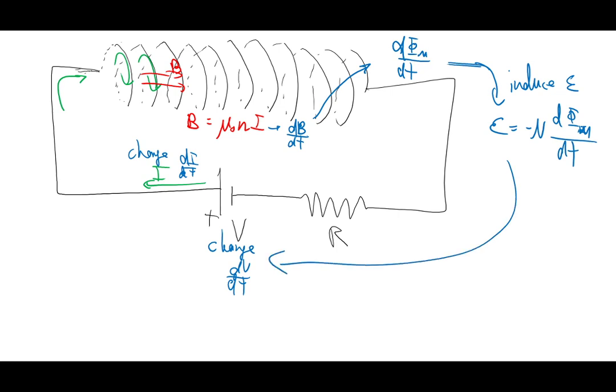which would then affect the voltage across the coil. And because of Lenz's law, you know that this is going to oppose the initial change. And that's why we call this phenomenon self-inductance, right? It's creating a changing magnetic field which then induces an EMF on itself. Your textbook also goes through this other thing called mutual inductance, which involves two separate circuits, but we're not going to get into that in very much detail. We're going to focus on self-inductance, or in most cases, inductance, that we're just referring to.